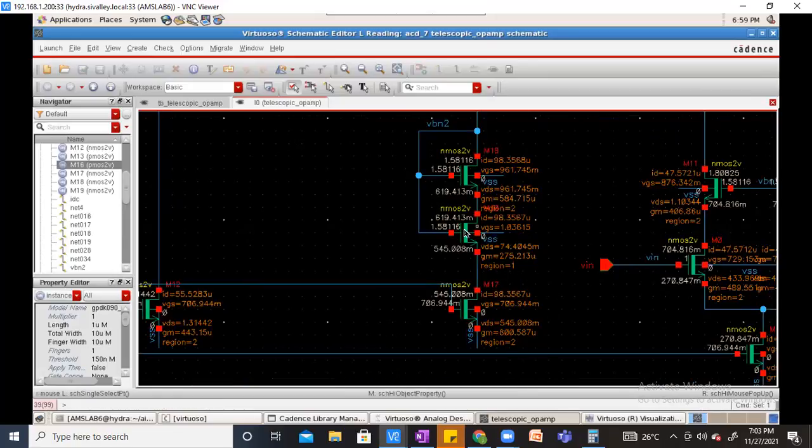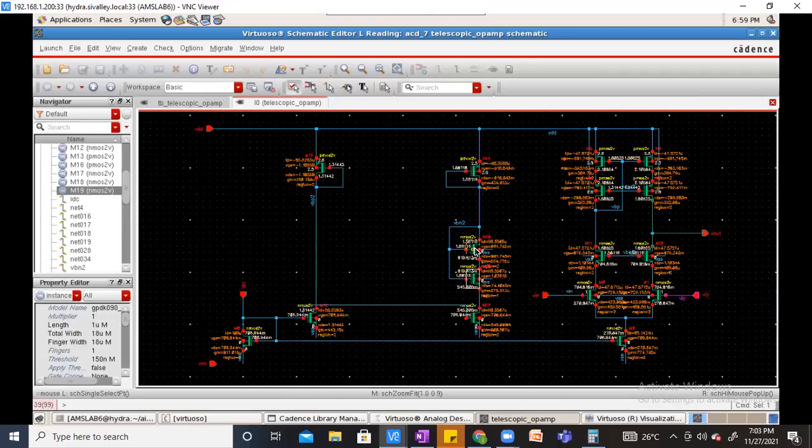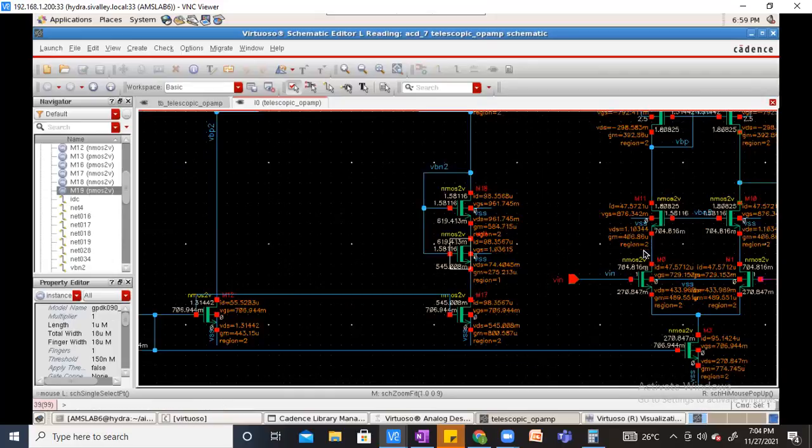So essentially, this we have used, or else you can delete it also, as this is not needed, because this particular MOSFET will have enough overdrive voltage here. You can see it here, right? So how much do I want here? VGS is 876 millivolt. Plus, let's say VDS is around 400 here and 300 here, like 700 plus 800. So 1.5 volt minimum I want at this point.